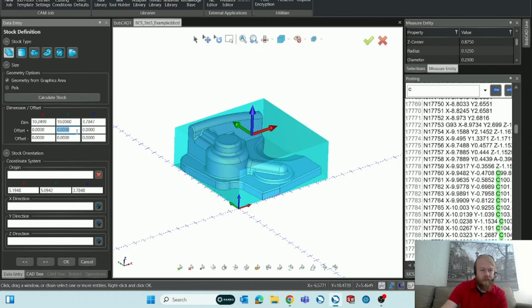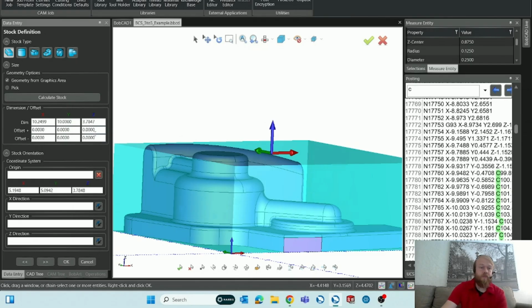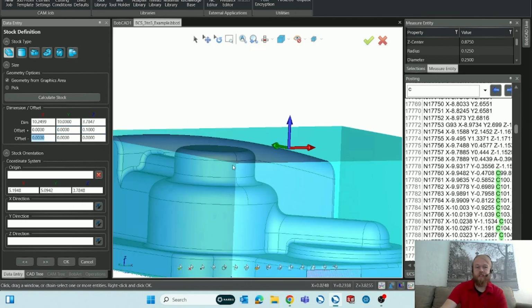So then from there, it can be really helpful just to show you if we're doing a facing operation first. I can type it in the positive Z direction. I can click on 1/4 of an inch, or usually maybe 100 thou in the positive Z direction to do a facing operation first and be able to face that off before our milling operation there.